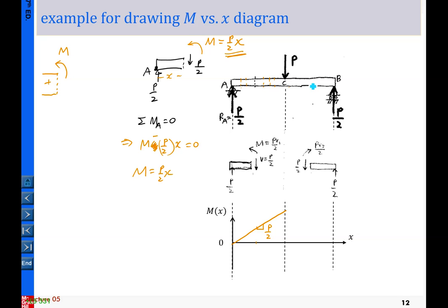And so say for this one I pick these sections, and then the free body diagram is simply like this here. Okay, and this is a section we come up with, and then again this is the previously calculated directions there, and that is the force given here. So by doing so, you can see the bending equals this. Okay, so let me recite this again. For this face left cross section, we have the bending equal to P over 2 times X.